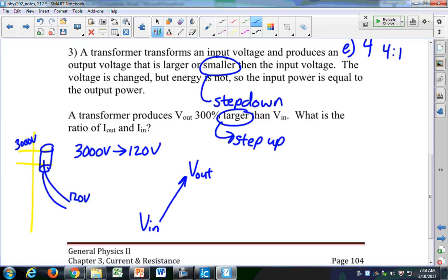There's nothing going on in the transformer. It's a completely passive device. So that means that there's no energy going into the transformer. It's just a can. It's filled with mineral oil mostly, and it has two coils of wire sitting next to one another. They don't even touch. Current comes in one coil, and then current comes out another coil. So with this step-up transformer, you must be asking yourself, where does that energy come from, right? If I'm increasing my input voltage by a factor of 3, by 300%, where the heck is that energy coming from? Aren't you asking yourself that question?